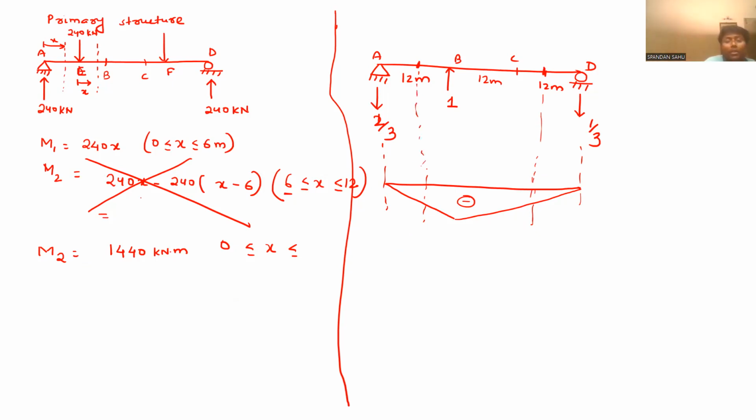Because your equation is like integration of small m, capital M, you have to multiply. For this, your x should be unique for small m. From where you are writing the bending moment M1 as 240x, from there only you have to write small m1, considering x from that joint only. Then only the convolution will hold good with the same lower limit and upper limit.